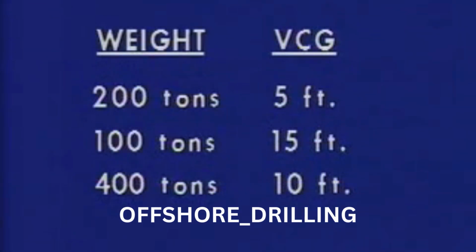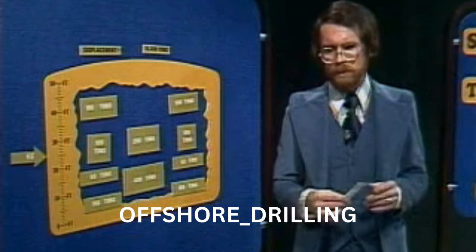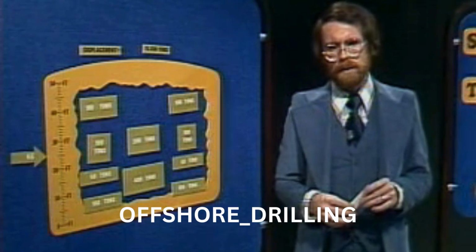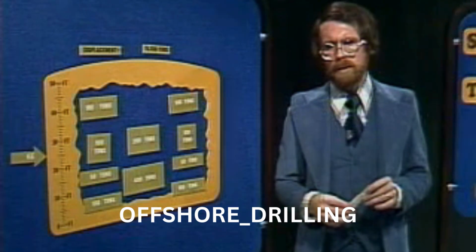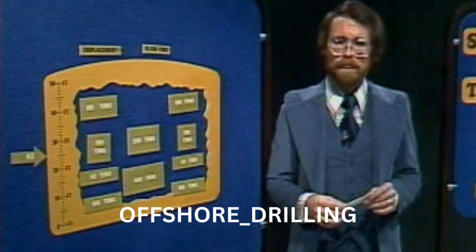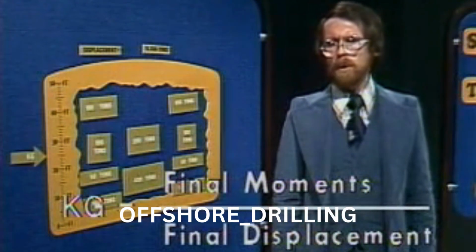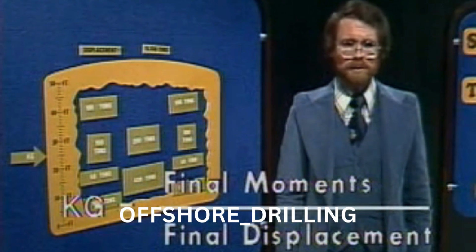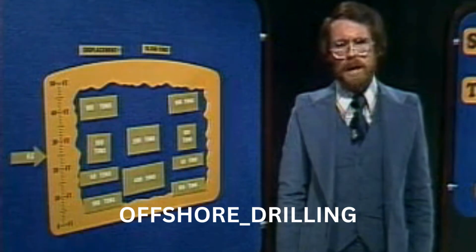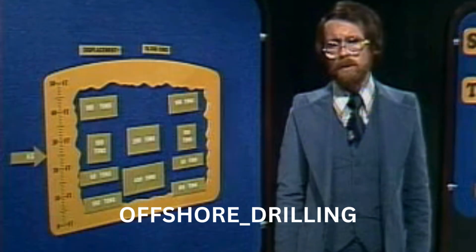the new kg? To solve this problem, we'll use the same method as we used with the first problem, except that we will be removing weight this time. Since we are reducing the displacement by removing cargo, we will be decreasing the total moments. Here's the formula, same as before. Kg equals final moments divided by final displacement. To figure the final moments, we'll simply subtract the moments for the removed cargo from the moments for the vessel and all of her cargo.